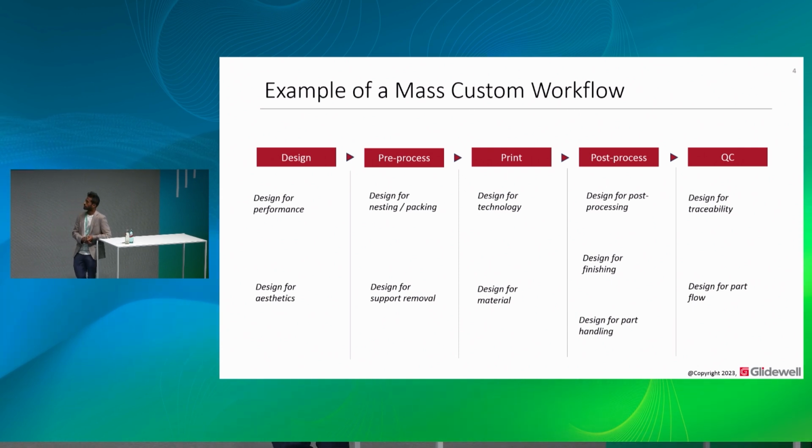The way we make those is we design the base of those dental models to interface with certain trays and certain fixtures that help us move these parts along in an automated or semi-automated way through our factory, from process to process. And we standardize the part ID on each of those dental models so that it's always on a particular face, facing some kind of vision camera or data matrix camera, so we can track this at every step of the process.